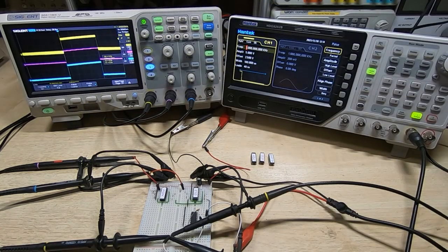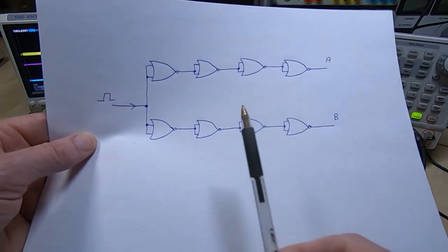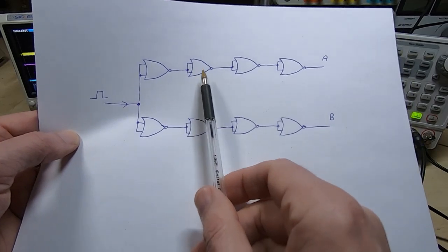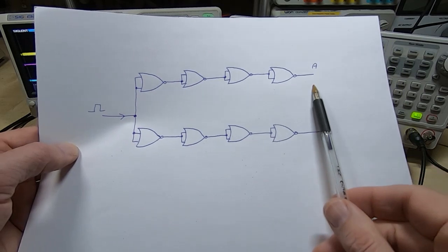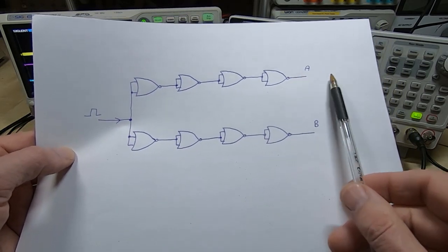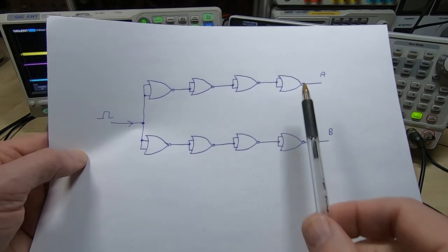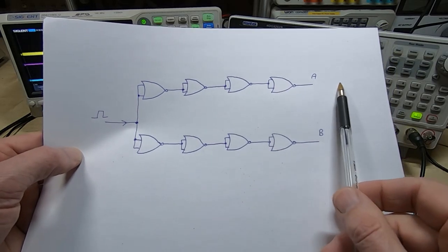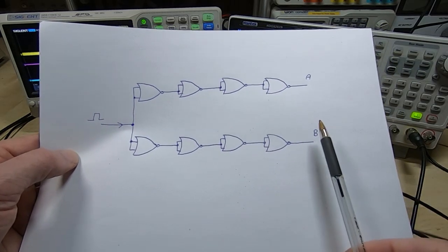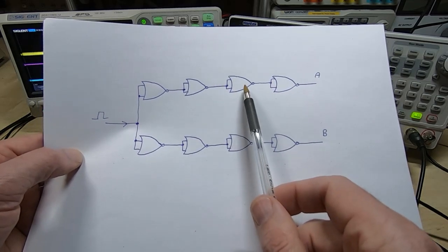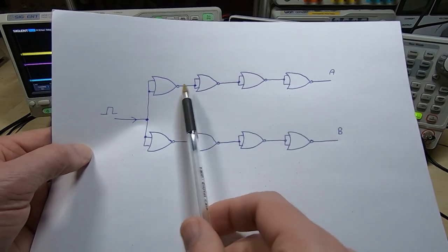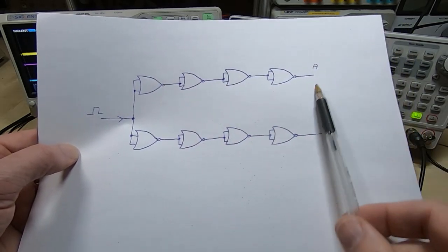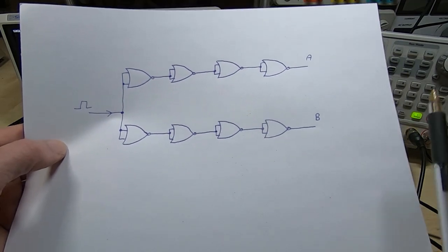And of course, if you start getting devices that are in a sequence, then if a particular device or devices start to fail, then the overall timing effect is multiplied, and you can end up with issues. You might find that you've got a RAM that's failing a test, for example. You change a device and it starts working. Doesn't necessarily mean that's the only device you've got problems with. Another one might be failing, but the overall operation might then be fast enough for it to work.